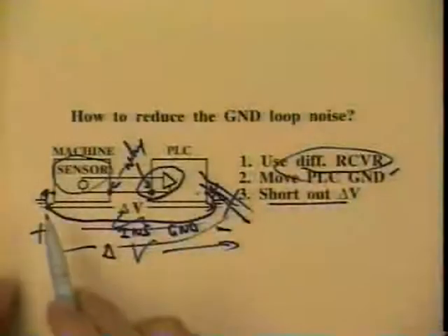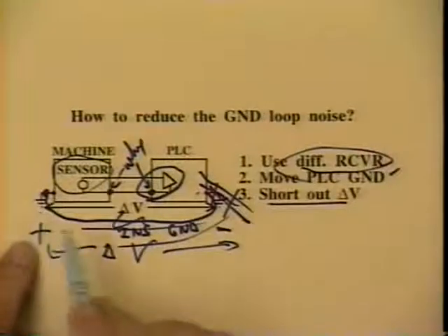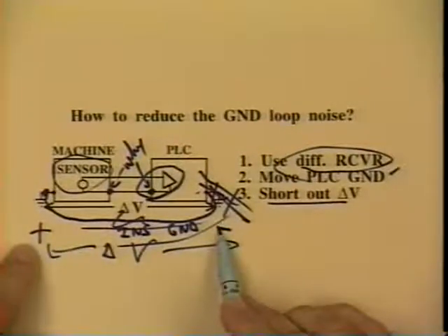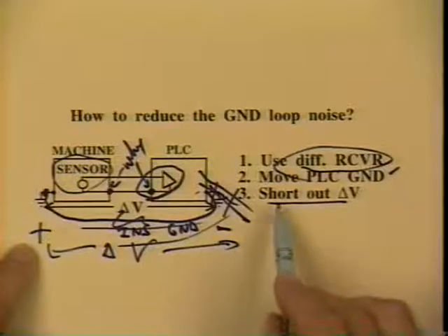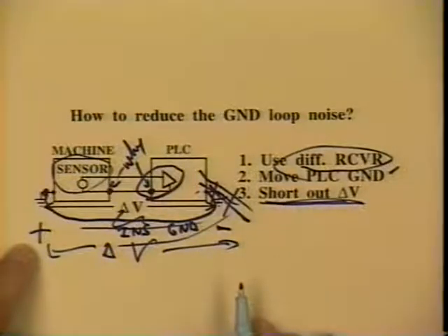And we're going to think we're going to short out that voltage, but we're going to be adding a few pounds of copper in parallel with a few tons of steel. And it's not going to make that much difference. We're going to need to lower that resistance by at least a factor of 10 in order to see a big improvement, and it's likely not going to happen. So what I'm saying is, if we see a large amount of steel connected between where the machine is grounded and where the programmable logic controller is grounded, that is already a low resistance connection. We're not likely going to make it much lower than that. So I don't think we would want to try the technique of shorting out the voltage difference.